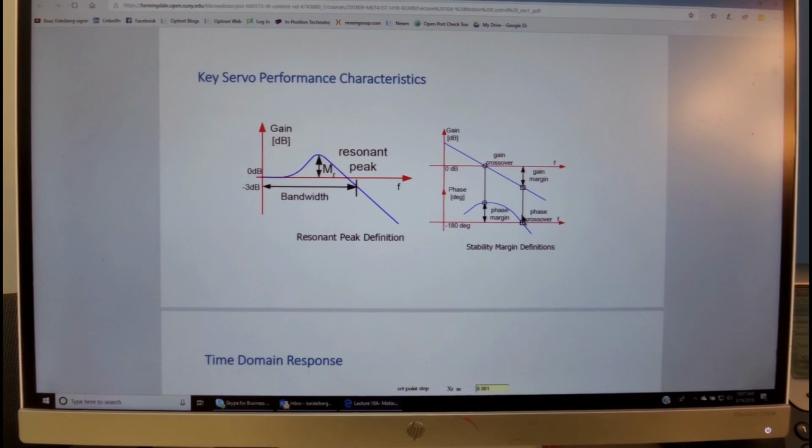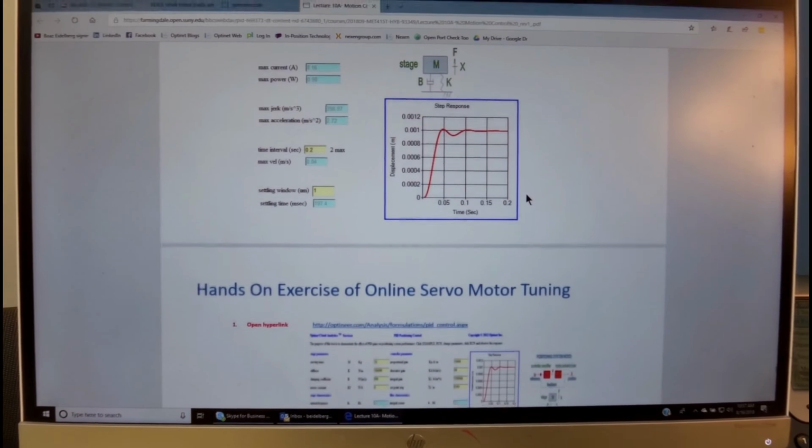And if we go to the intersection of the minus 180 and the phase chart, bringing in a vertical line, it intersects the gain chart at this point, and this is a negative gain margin, which is good for a stable system at about minus 15 dB.